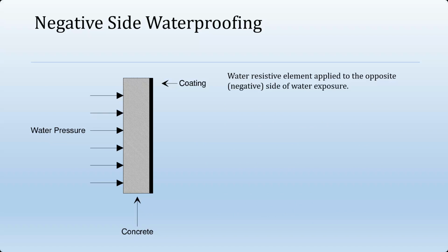I think many have probably seen how some homeowners, or maybe some commercial property owners, would paint the interior side of their basement foundations. I would posit that many of those have, at the bare minimum, or at the most, frankly, damp proofing, which again is really the lowest common denominator. But we've seen examples where the paint eventually starts to alligator crack, because the 100% RH source on the outside is going to move through that concrete, which may not have as low a permeance as the aforementioned waterproofing, or for that matter, damp proofing, and delamination occurs as a result.